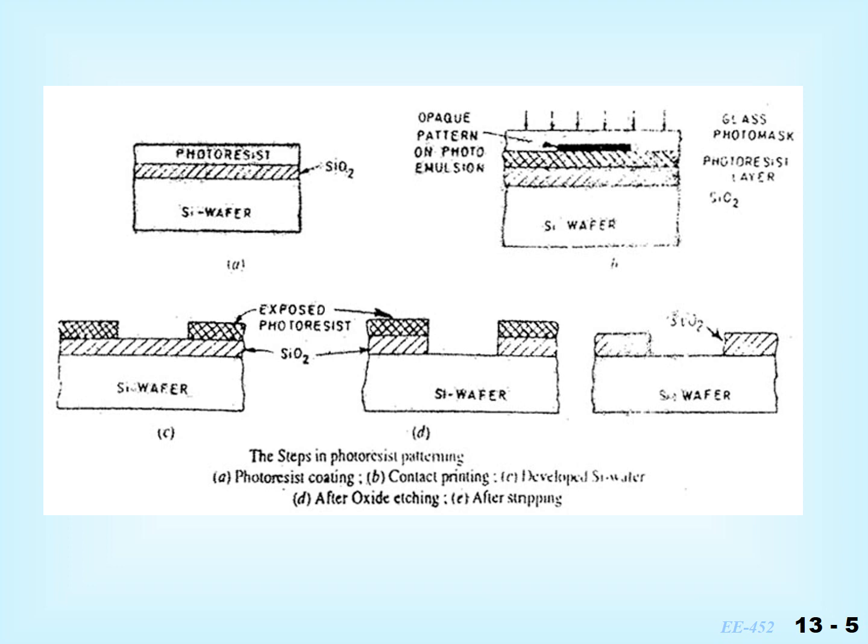After this, in the etching process, the etchant is an acidic solution which is used to remove silicon dioxide. That means the silicon dioxide which is now exposed will be removed, whereas the photoresist will protect other regions of silicon dioxide. Now the last step is removal of this photoresist, that is photoresist stripping.